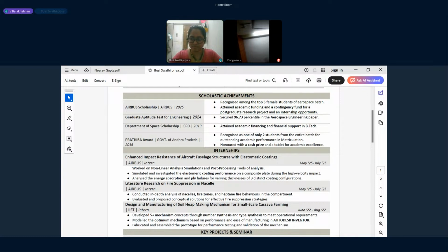So it is taken not from the combustion chamber. Combustion chamber temperatures are very, very high. It is taken from third or fourth stages of the compressor. From there, tapping is taken. At fourth stage itself, the temperature is quite high. It is taken there and then taken to that.